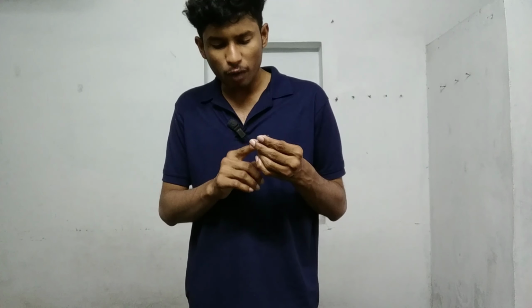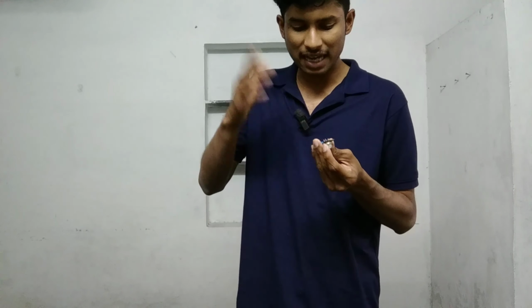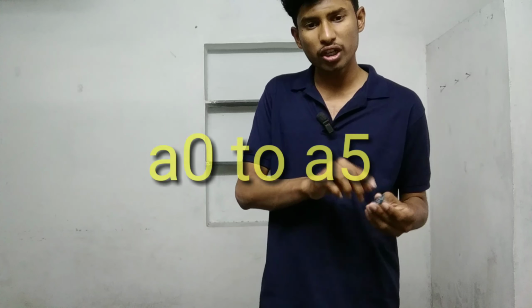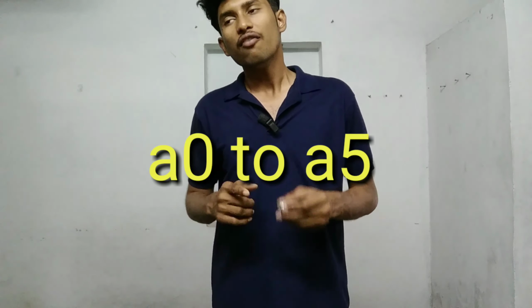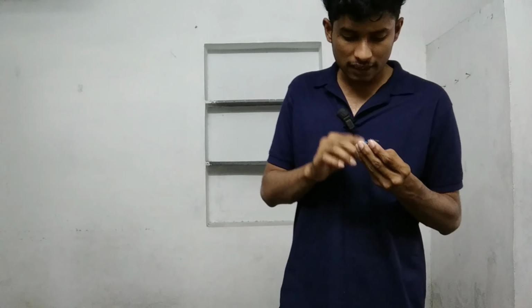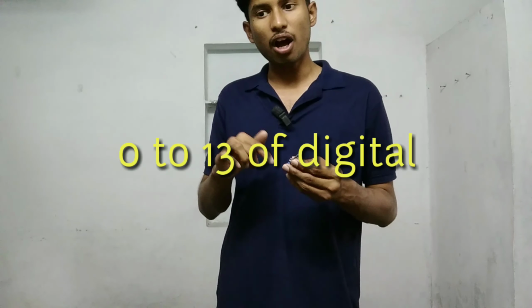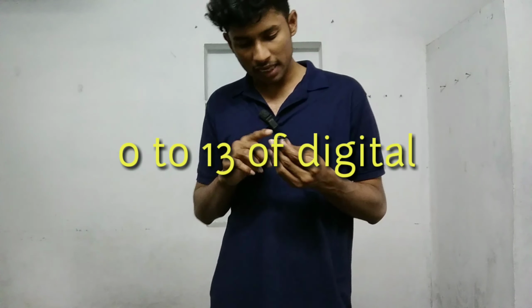This is an analog as well as a digital sensor, so it has analog and digital outputs. If you want to get an analog output from this sensor, you should connect it to the A0 to A5 pins of the Arduino board. If you want to use the digital pin, you should connect it to the 0 to 13th pins of the Arduino board.